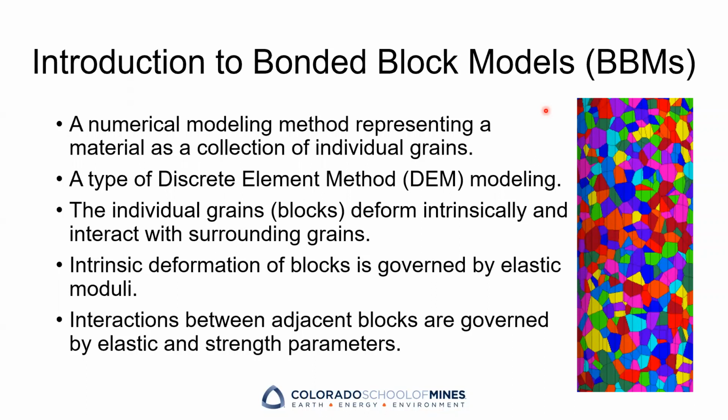The macroscopic behavior of the material sample during a simulation depends on the microscopic behavior of the smaller blocks. BBMs are a type of discrete element modeling method, meaning each of the blocks deform intrinsically based on a set of input parameters. But blocks also interact with adjacent blocks, in which interactions are governed by elastic and strength input parameters.